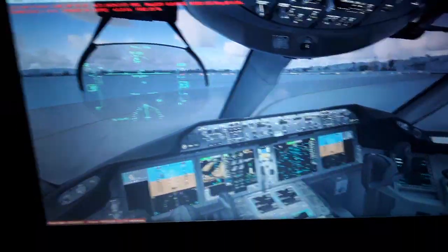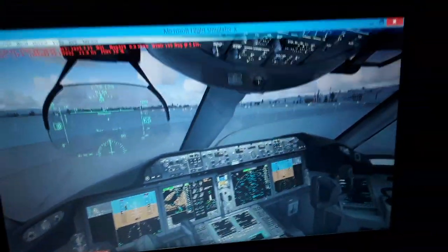It's going to give us the takeoff speeds V1, V rotate, and V2. So we're going to have the rotation speed and takeoff speed V2 plus 15 knots. So we're going to start climbing. We're going to pitch the aircraft. We're going to have a pitch attitude in the takeoff rotation of 9 degrees or less, and full takeoff thrust power setting. So we're going to have a pitch attitude like this, and we're going to start climbing.